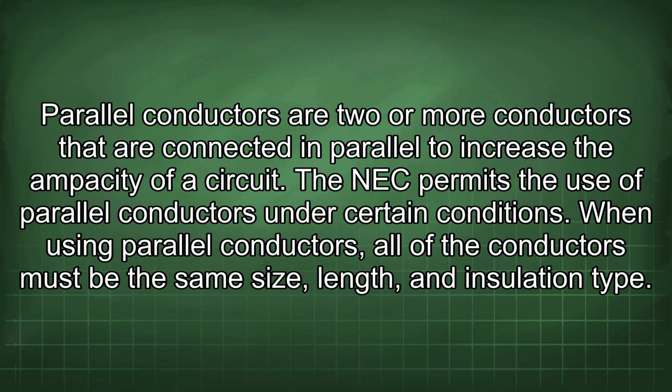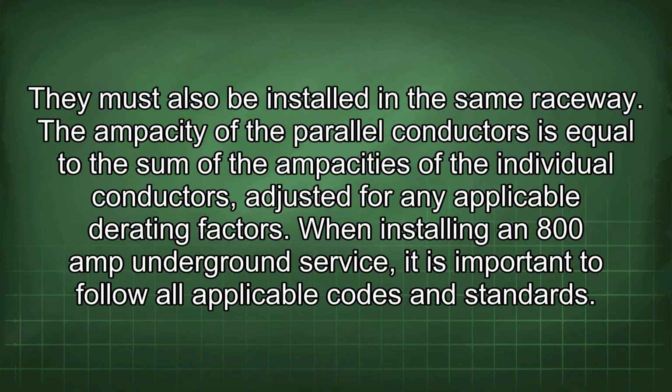Parallel conductors are 2 or more conductors that are connected in parallel to increase the ampacity of a circuit. The NEC permits the use of parallel conductors under certain conditions. When using parallel conductors, all of the conductors must be the same size, length, and insulation type. They must also be installed in the same raceway. The ampacity of the parallel conductors is equal to the sum of the ampacities of the individual conductors adjusted for any applicable derating factors.